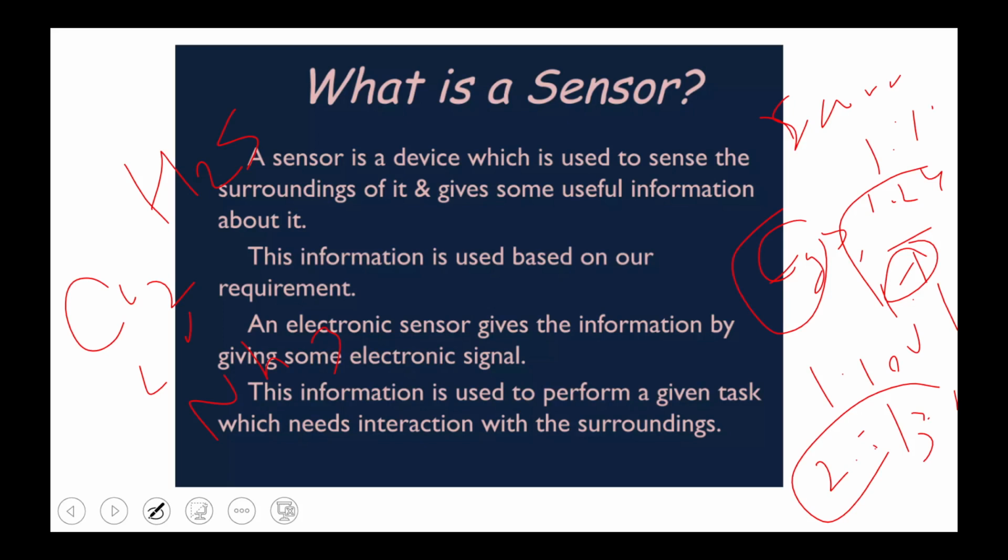So you have to protect yourself before entering the sewage line. You have to wear the oxygen cylinder and mask, so that during inhaling nothing enters, and you can protect yourself. But people go into the drainage system without any precaution and without knowing the concentration, and they die.